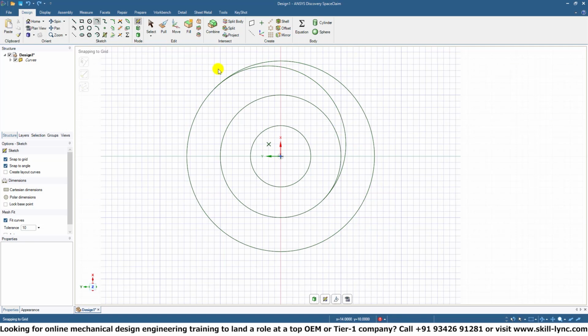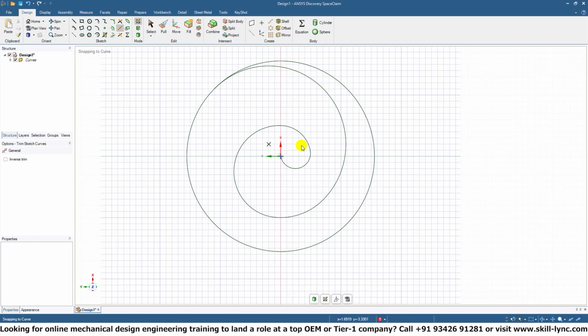The problem with this, the reason why it wasn't trimming away, is because it was a complete arc, a complete circle, because when I actually put a point over here, went around to this point and continued from that point on, it didn't sort of segment the other circle or the other arc to create sort of a closed loop. You gotta give it some space, some leeway in there. And now that I've done that, it should let me cut this arc, trim away this arc, and there you go, we have a little sort of arc segment.